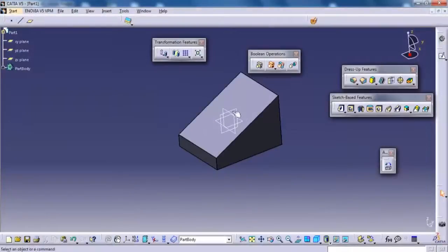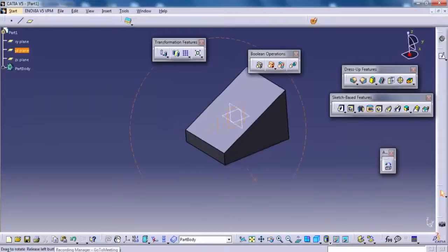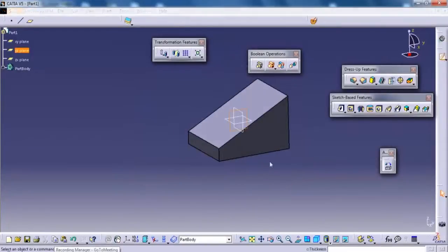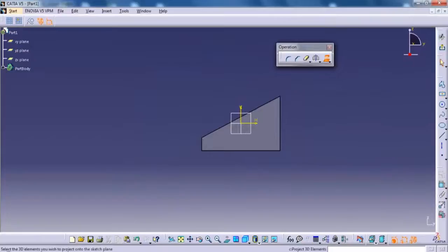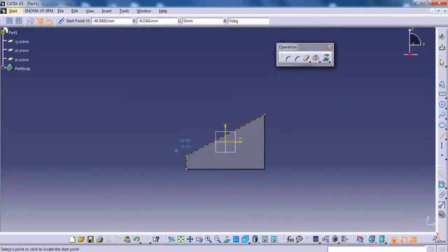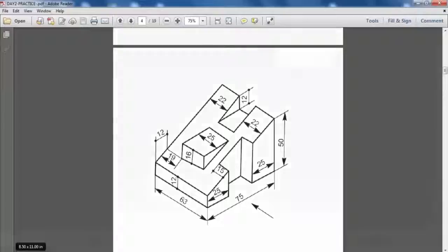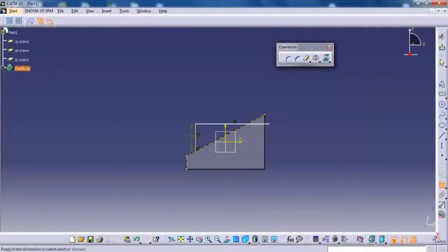So I'm just going to this plane, this one. Now going to enter into the new sketcher, project the entity, this one, construction, again this one. After that, just create one line segment like this, and now create one more line segment which will end up like this. Now I'm just going to create a distance of 12 millimeter. Just provide one distance to second. It should be 12.